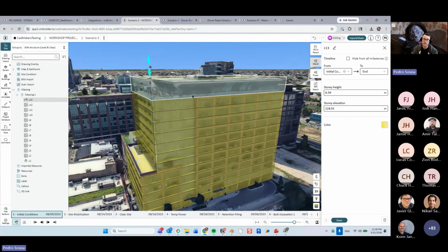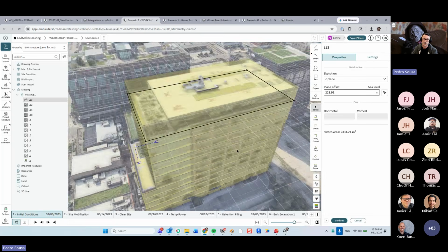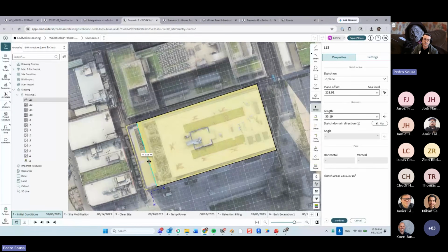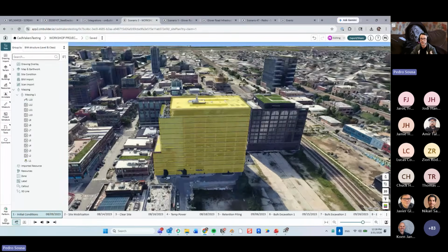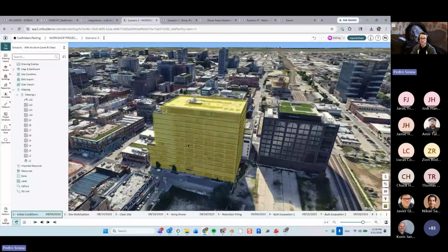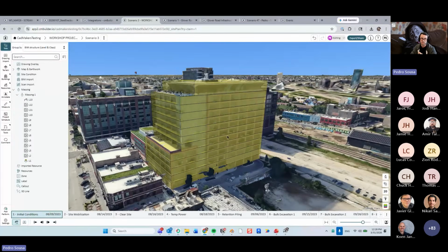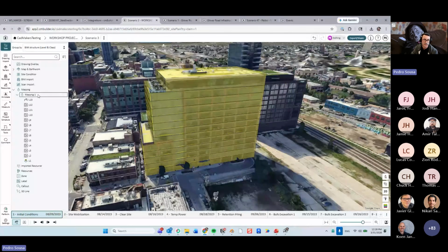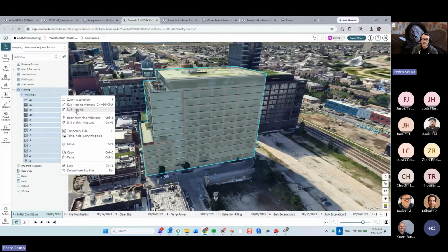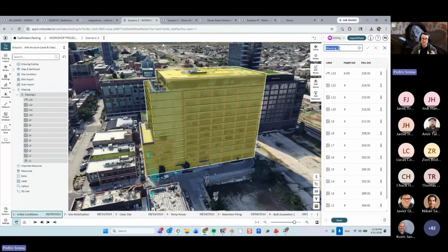And then on the level above, the last one, I'm going to edit the sketch and edit this guy over here. So now I have a colored shape for this level to represent work that is being done over here. I'm going to call this work front number 1. So I can go over here in my massing tool and edit this massing to rename it, so I can quickly identify on the tree structure what this massing is about. Let's say that this is interior fit out.